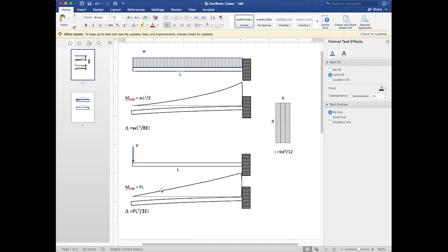So out on the job site, the project manager, lead contractor said, haunch up. So if you're putting in an LVL, you want to make sure that the high side goes up and the curve goes down at the bottom, and the whole system will come to level when the dead load is actually applied to the LVL. Well, when it comes with a haunch up,